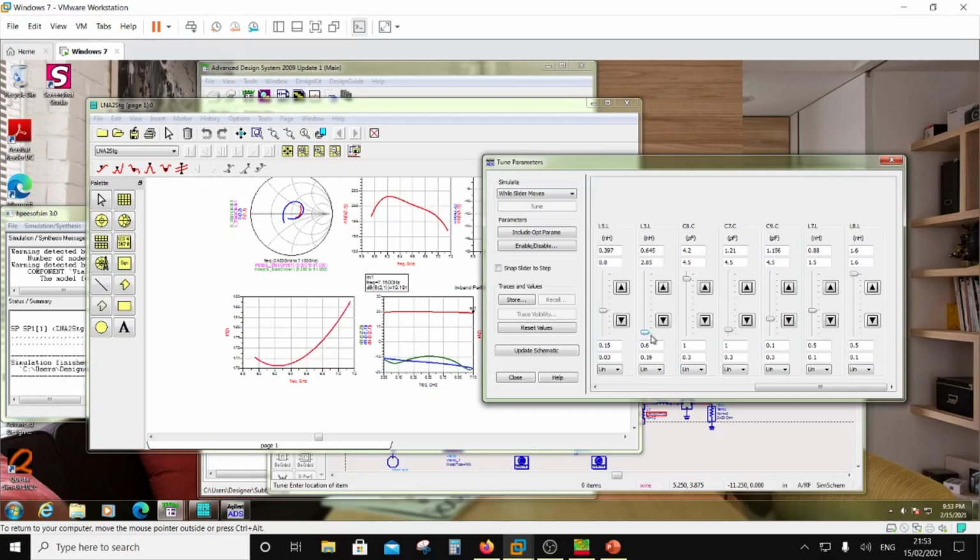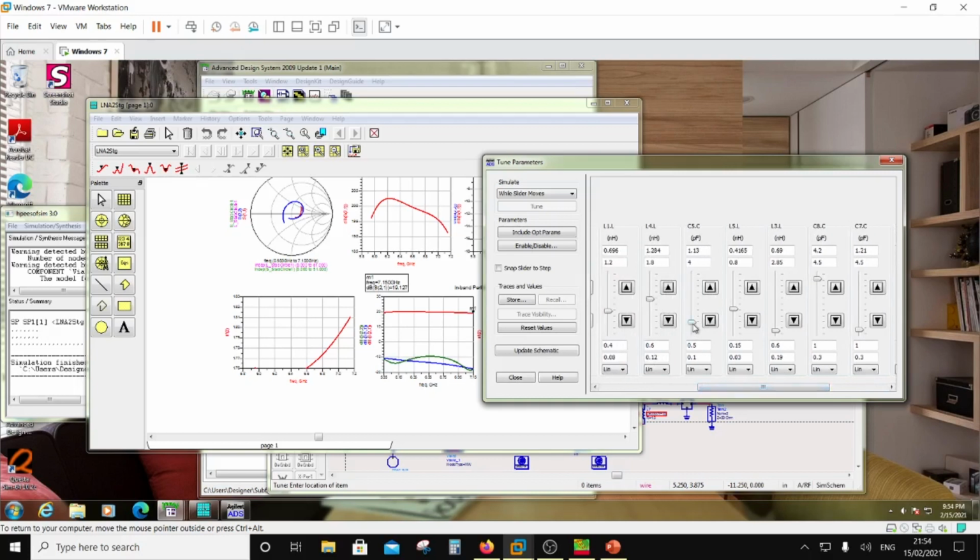And this one is affecting your noise figure, right? So this one is affecting your input match, so you are mismatching it, correct? And this one is gain, and this one is directly hurting you on the noise figure.